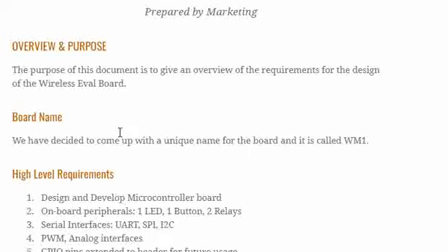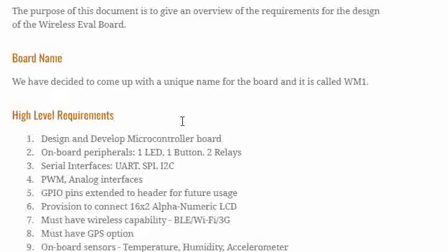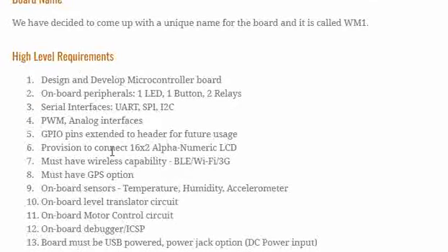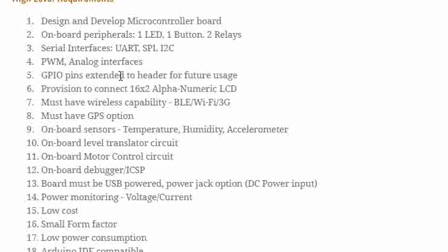And then there will be high level requirements. So for our project, WM1, the requirements are: design and develop a microcontroller board. You must have onboard peripherals: one LED, one button, and two relays must be there. That's the requirement. And then you should have serial interfaces, UART, SPI, I2C on the board.